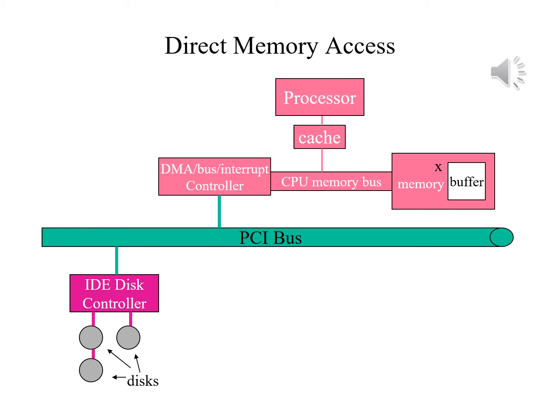Programmed input-output, where we transfer data 1 byte at a time into a controller register and then use a general-purpose register to watch its status bits, seems like an awful waste, especially when you consider how much data we are moving these days. Back in 2001, JPEG files could be 100 kilobytes, and audio files, like the one that you're listening to now, could be close to a megabyte in size. These days, they can easily be 10 times that size. Moving that much data 1 byte at a time would seem to take forever.